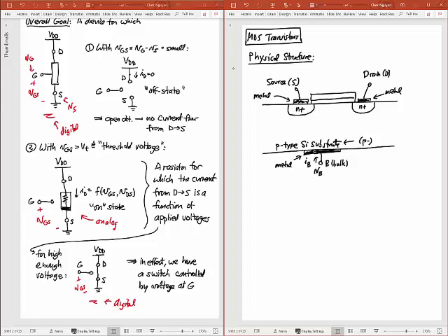And that gate is effectively a conductive portion up here. Right, so this is actually a conductive portion that's either a metal or a heavily doped polysilicon. So I'll call this my gate, G, and I'll just indicate that this is heavily doped polysilicon. Polysilicon just means that instead of a single crystal, I have many small crystals of silicon that have been compacted together. Okay, and so by heavily doped, that means I can also call this an N plus region here.